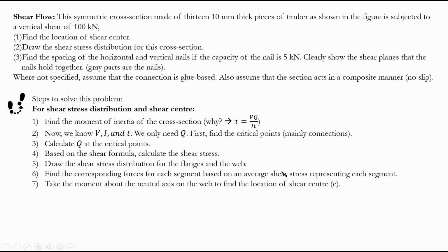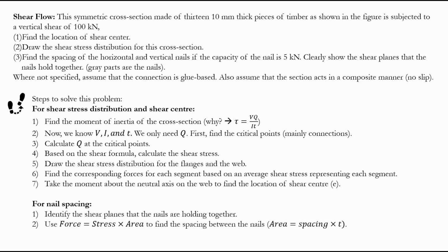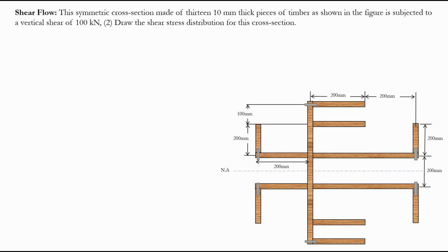This is about shear center because we have to find the corresponding force value to calculate the location of shear center to avoid additional twist. And for nail spacing, again, we are going to identify the shear planes and use the force equals stress times area formula to find the spacing between the nails. Now let's start with our first step.